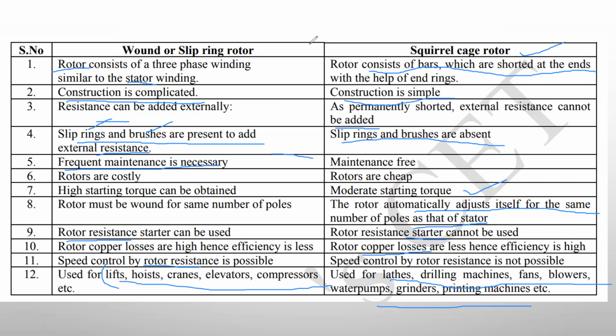So today we have seen the working principle of the three-phase induction motor. It has two parts inside: one is called the stator and one is called the rotor. The stator is of two types, star connected and delta connected. The star winding is displaced by 120 degrees. When a three-phase AC supply is given to the star connected stator, it produces a balanced sinusoidal rotating magnetic field. This rotating magnetic field will sweep over the rotor. So according to Faraday's law of electromagnetic induction, an EMF is induced in the rotor conductor.